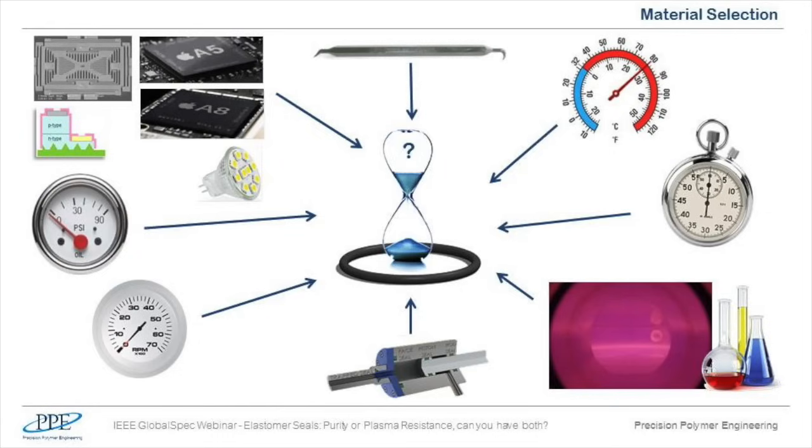Choosing the right material for the right semiconductor application can be extremely confusing and risky, and we help our customers pick the right material for the right application. But when specifying a sealing material, it is always an advantage for us to know some details, such as operating temperature, the expected lifetime, is it a plasma process, and if it is, which gases, which chemistries, the type of the plasma, or what other chemicals can be used in the process, the type of seal, is it dynamic or static, what's the pressure, etc.